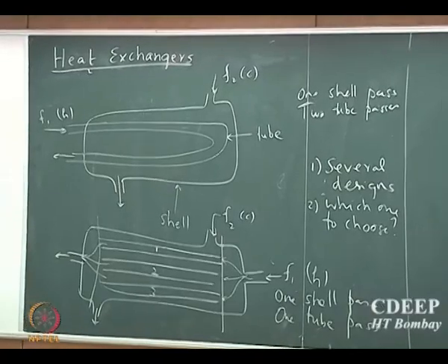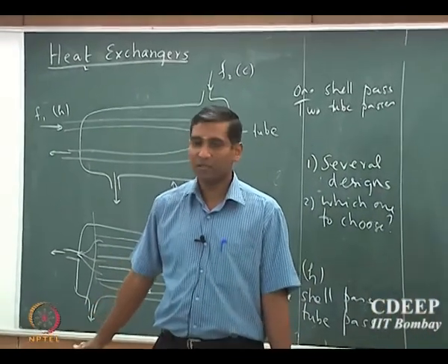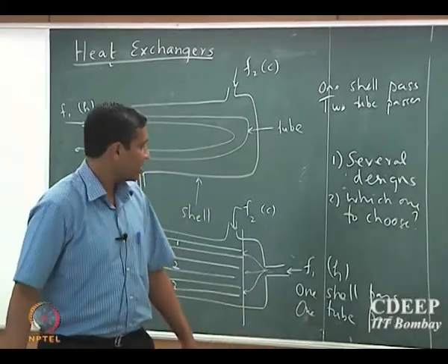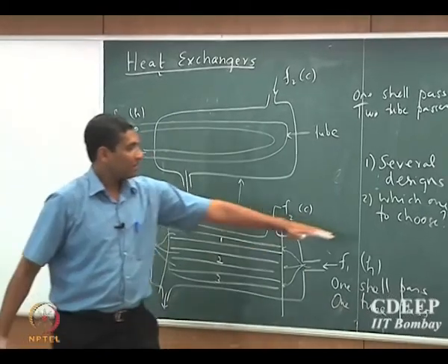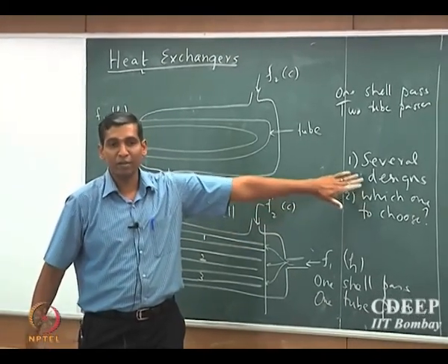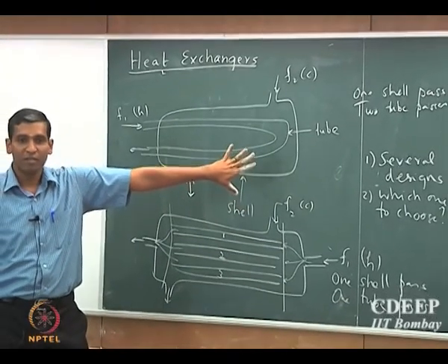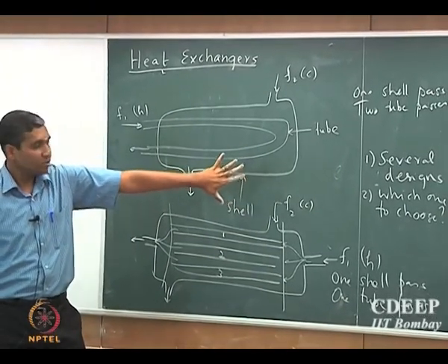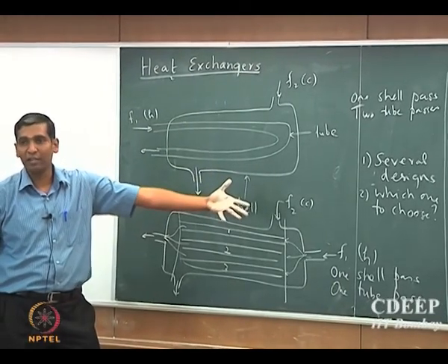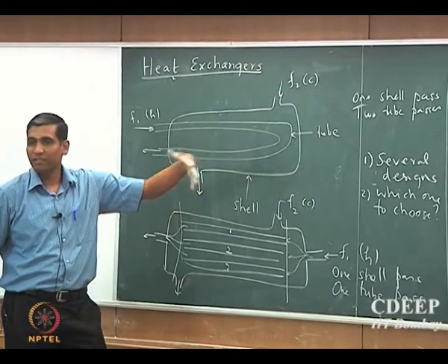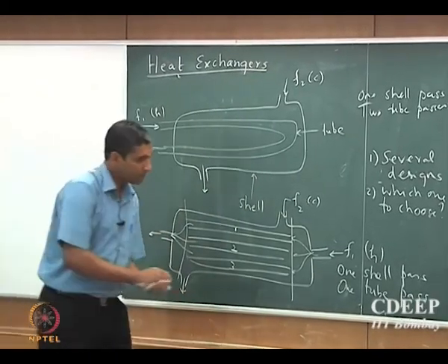By the way, it is important to note that most of the heat exchange processes in all the industries that I had listed actually use shell and tube heat exchangers, because you have an extensive amount of flexibility in how you want to design in order to achieve the heat transport that you want. Okay. So it gives you a lot of flexibility in terms of both increasing the heat transport area and keeping the pressure drop and the efficiency in mind.